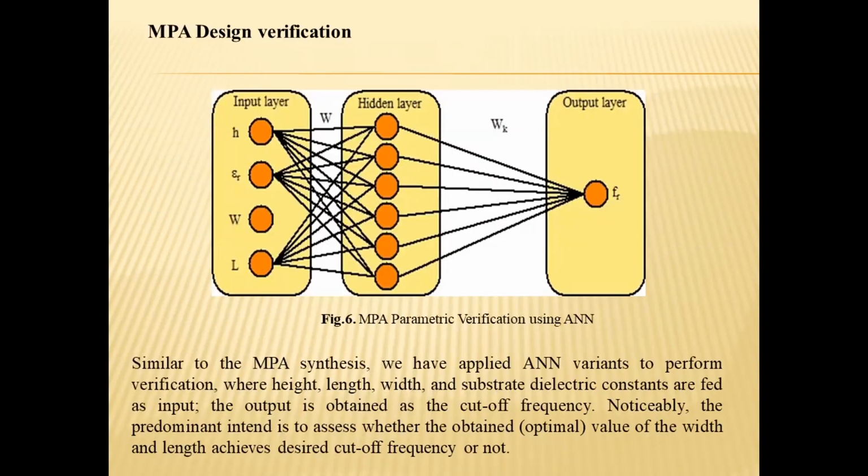In this work, our aim is to identify the optimal dimensional parameter of the rectangular microstrip patch antenna for ultra wideband application. For this, our antenna was designed with the parameters: height of the substrate, dielectric constant, the patch width, and the patch length. At first, the training parameters were obtained by varying dimensional parameter while maintaining the dielectric constant and height of the dielectric constant. Frequency values were obtained. The obtained results are given in table number 1.